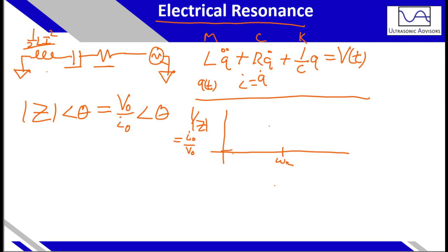So velocity would actually be 0 at low frequency and begin to increase. As you get to your resonant point, you still have that resonance response, and you approach a velocity of 0 as your displacement continuously decreases as the frequency increases.